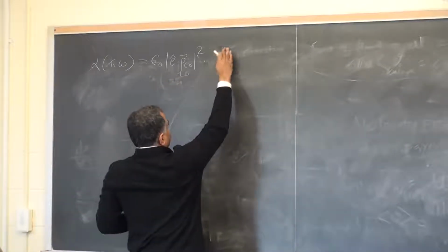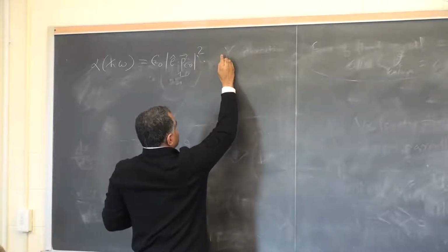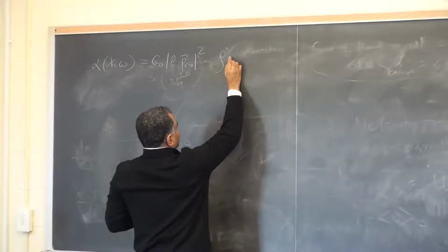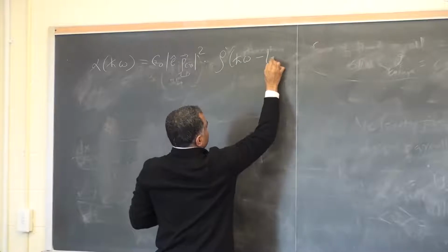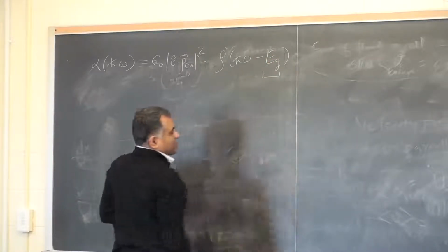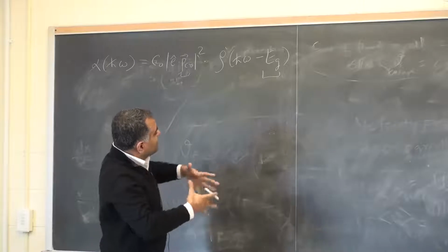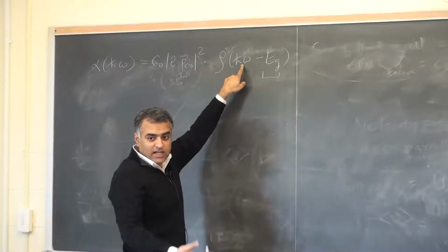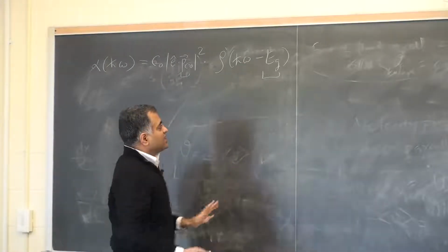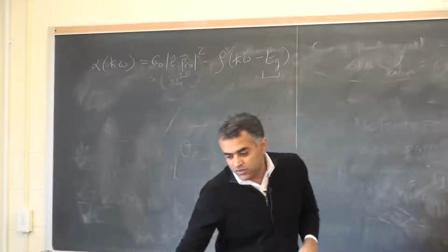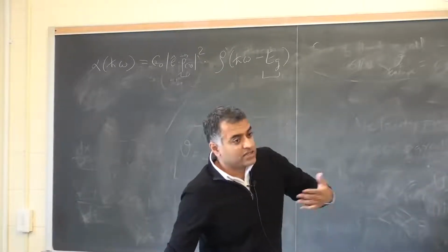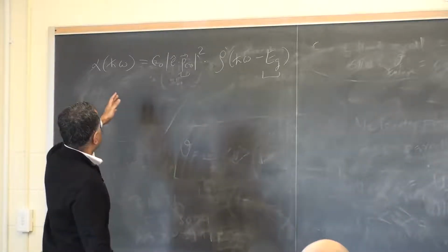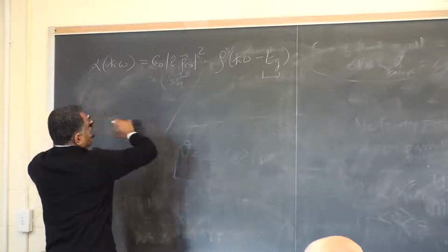And then finally, what we'll have here is a joint density of states. In general, some books would write it as rho, the density of states, which combines all the physics of the semiconductor, which is buried inside the band gap, and some of it is buried outside here, and that of the photon. And the photon has an energy h bar omega. So it's a joint density of states that couples the light or the photon with the matter, which is the electron in the solid. So that's a joint density. And what I'm trying to say is this is what we may call an equilibrium absorption coefficient.